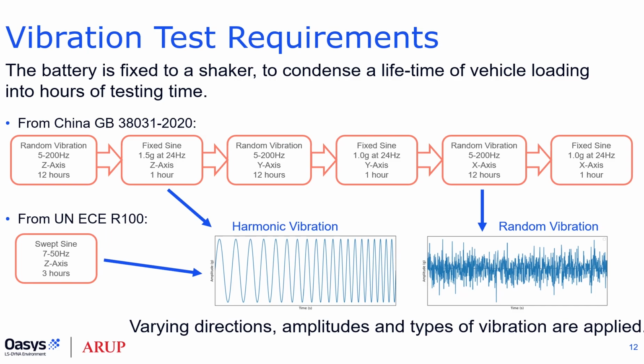Both tests require that the battery still functions after the test, so any failures within the battery that would prevent it from functioning are likely to be due to fatigue, since the testing will apply many thousands of cycles of loading to the structure. Therefore, we need a method in LS-DYNA to reproduce the vibration test and predict the fatigue life of the components inside the battery.